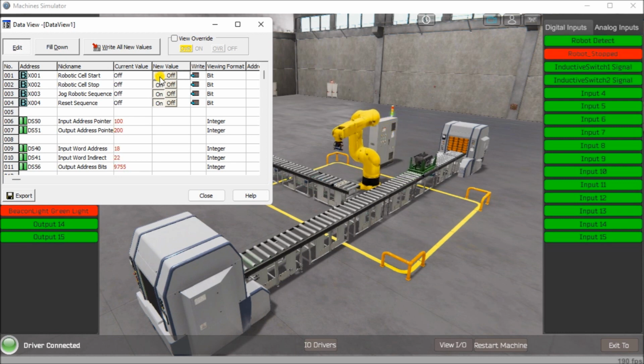The other thing we said we can do is at any time we can actually stop it, and then we can actually jog our sequence. So if we jog it, you can see right now we're at the first step. Step 1, step 2, 3, we put it into the pallet. Now remember, we're not controlling from the input side, so we're just controlling the outputs directly. And this is a great way of testing the actual logic itself. There's 4.